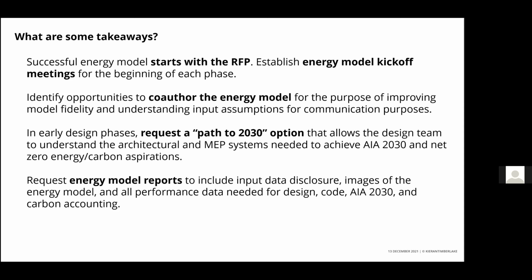And then lastly, those energy model reports are really good QA, a quality assurance measure, to understand everything looks good. That the energy model actually is your building and it's being represented correctly can go a long way. And having that as an archivable document is always useful to go back to when you're reporting 2030 data, you've got to dig up your energy model report and find out what that EUI was. So having that in PDF or whatever is extremely useful.